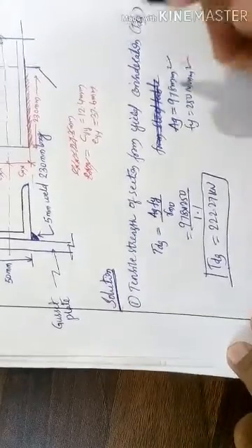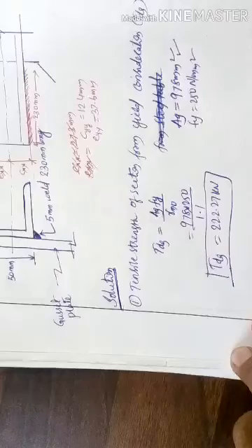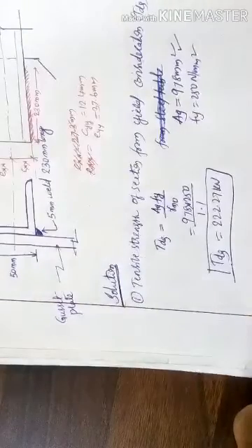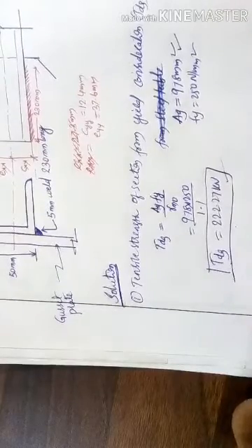Okay, so here the area is given, so no need to refer to the steel table. You can even cross verify this one. The angle size here is given as 80 by 50 by 8, and the area 9.78 cm squared, so 978 millimeters square is given. If it is not given, you refer to the table and take the area. So here the area is given, take it directly and calculate. This is TDG.